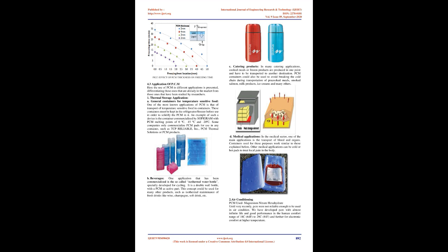Phase change material PCM installed in telecom shelter will absorb heat in case of unavailability of power, minimizing or eliminating use of DG sets. PCM will get recharged when power source is available. Thus, PCM stores energy using a cheap source of power and releases it when that cheap source of power is not available, thus saving on diesel cost. Telecom shelters PCM. 4. Transportation.